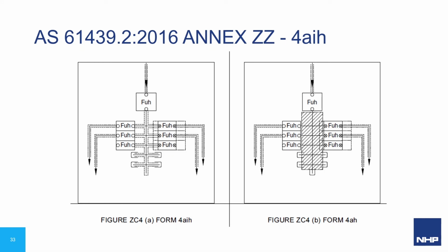The functional unit housing must maintain IP2X protection on the line side as before, and now additionally, the load side of the miniature circuit breaker or molded case circuit breaker must maintain IP2X protection, either by its design or the addition of terminal covers. The terminal covers must achieve IP2X rating or better to be acceptable. This means extra care is required by the installing contractor to maintain IP2X protection when making their terminations into the assembly on site.